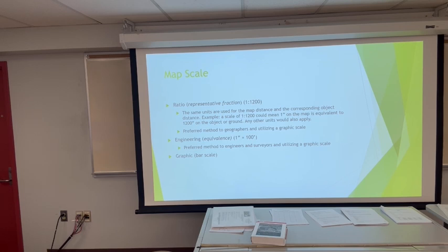This is the preferred method for geographers, and they also utilize the graphic scale. The engineer or equivalence type scale is what we're used to, like 1 inch equals 100 feet, for example. We have the engineer scale. We did that drafting plat lab earlier in the semester. We used the scale to scale out our distances. So we have things like 1 inch equals 10 feet, 1 inch equals 20 feet, and so forth. This is the preferred method of engineers and surveyors, along with utilizing a graphic scale.